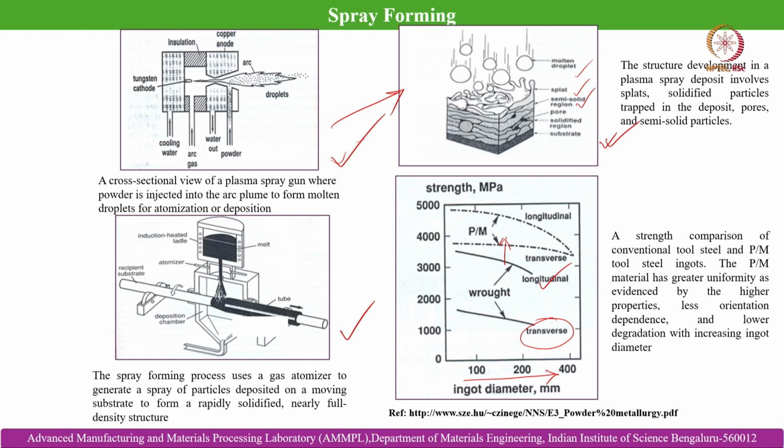So, those defects are inherently nullified in powder metallurgy routes, because we can control the morphology of the sintered part by controlling the morphology of the powder particle itself. That is also why we can control the orientation to a greater extent. If the microstructure of the powder particle consists of fine grain morphology, then we end up getting fine grain morphology with significantly higher mechanical properties in the sintered part. So, on occasions we can achieve higher mechanical properties than the wrought form of the same material.